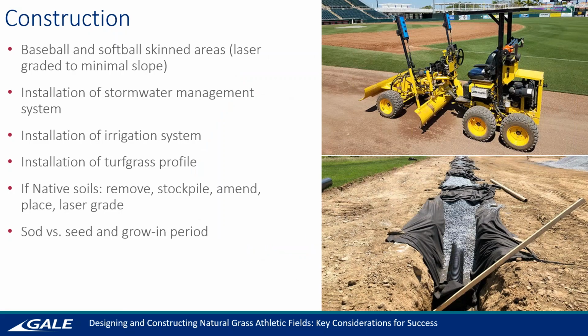All right, we're talking a little bit in construction here. So construction, first, some of these photos kind of give you a sense of what's needed. The one on the top right is kind of the main one that once you move everything around. These are the laser graders, and this is what dictates. You're not doing kind of general landscape areas here. You're doing high level athletic facilities, so you want to be able to have the planarity that you need, a consistent slope. And the one here is shown for baseball, which I talked about previously.